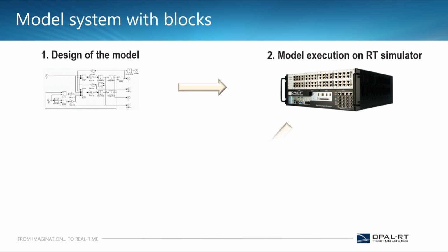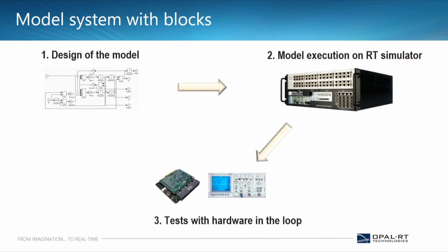Now, what is the next step? The next step is hardware interfacing. So this is exactly a closed loop performance we are going to do. We are taking a MATLAB model, burning it on a real-time platform, then again taking out results and giving them back to the MATLAB environment so that we can tune the parameters on the fly. For example, we want to introduce a fault at t equal to 10 seconds. Then we want to monitor whether the relay is properly functioning or not.